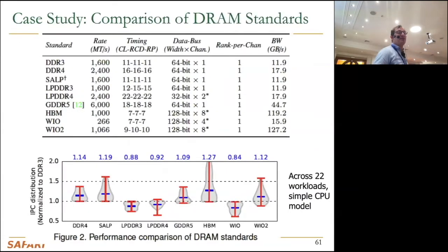And this is one example study you can do. You can compare different DRAMs for different applications, and you can see which DRAM is better for your application. In fact, we extended the study in a later paper that I don't have a reference for here. Maybe I'll reference it tomorrow. You can see that some standards are better than others for a given application. And these are averaged across different SPEC applications. For example, we show that HBM is much better than DDR4 on a majority of the applications over here, especially because the applications require high bandwidth. Okay, you can do this sort of study relatively easily. You can actually imagine different memory architectures and code them and see the effect.